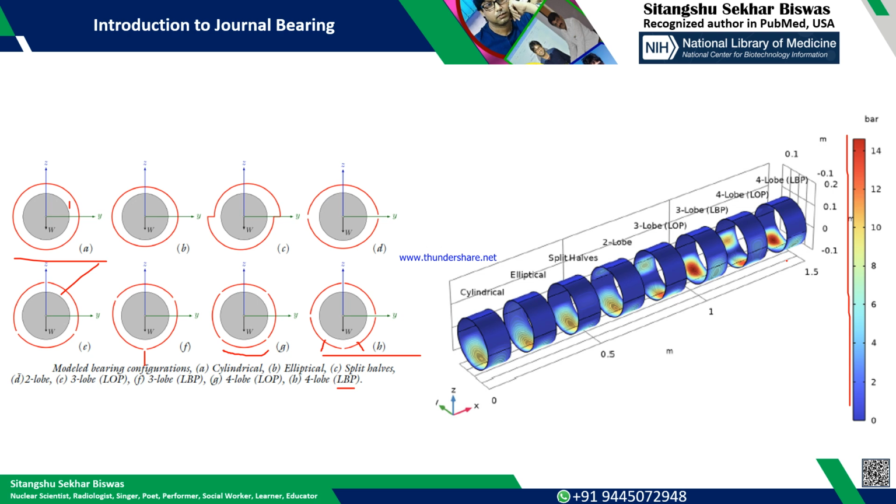this is, in starting itself, before starting, you can tell the forced mechanism to lift the shaft. So in case of this large scale vertical coolant pump, you might have seen very near to the impeller there will be a hydrostatic bearing.